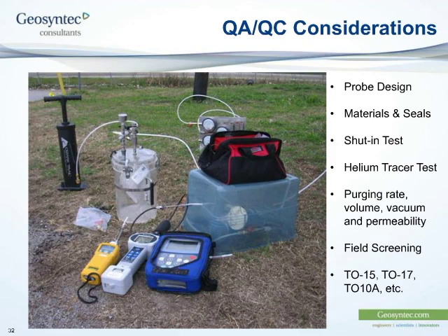But with soil vapor sampling, I could give a talk of almost an hour duration on just all the different things that can go wrong. If you're sampling groundwater and you have a leak, you get a puddle. If you're sampling soil gas and you get a leak, you can't necessarily see, hear, smell, touch, or taste it.